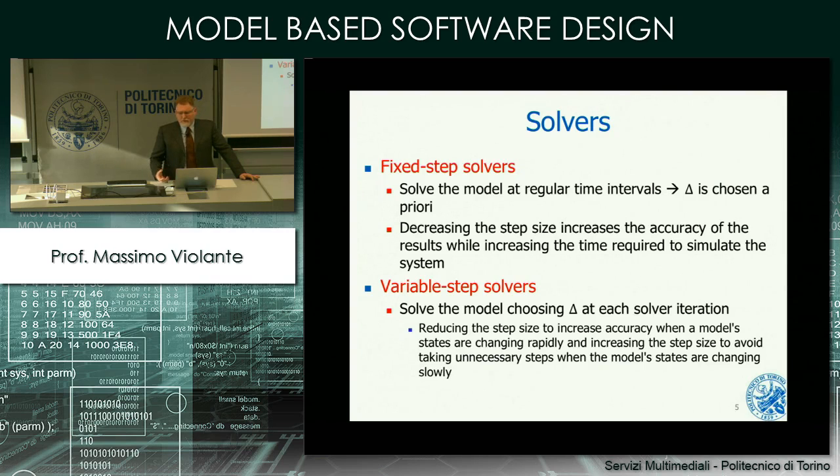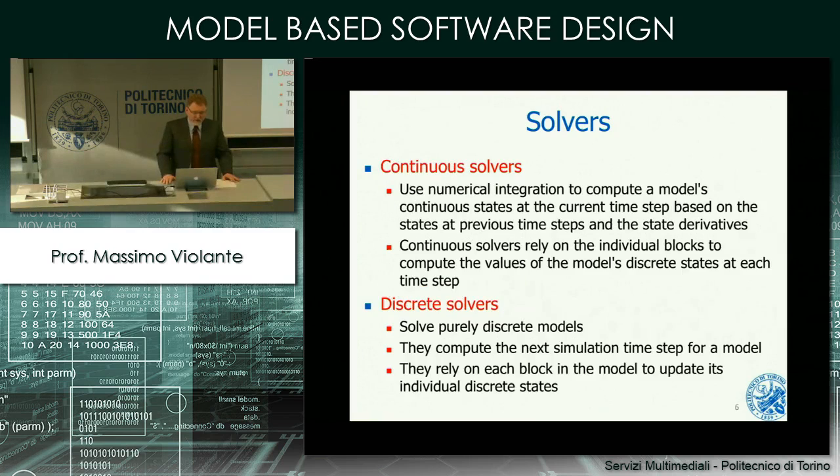You care about the model of the plant, so you are looking for the maximum accuracy, and so you just try to look into the best that Simulink can offer in terms of computation speed and quality of the results. And this is what is normally provided by variable step solver and continuous time solver.